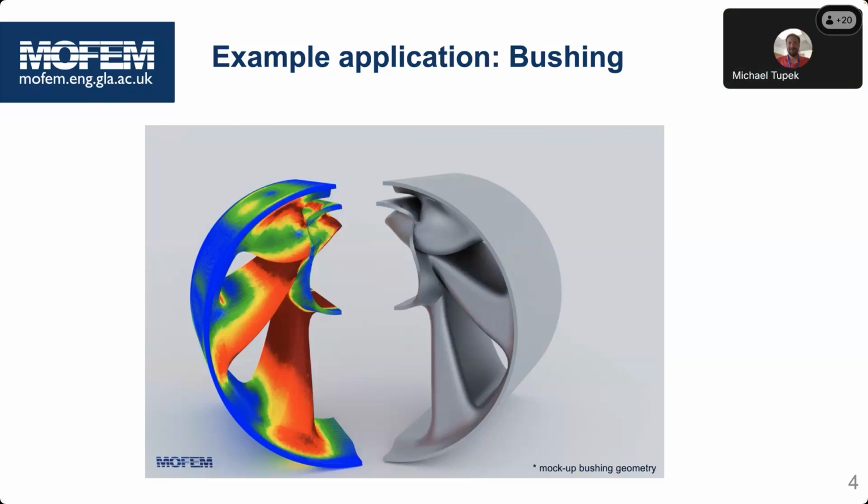So it looks like early on you guys were doing some pretty impressive stuff where you were explicitly representing the crack surfaces and evolving the front. And I'm somewhat aware that that's not trivial to do robustly. But more recently, it looks like you guys have been moving more to the cohesive insertion type of thing. I understand it's more elegant in the sense that you don't have to insert and change topology, but it has the limitation, of course, that the surface representation possibilities are limited, right? You're stuck on the surfaces that exist in the mesh, and that can add some bias and lack of convergence. So what is your sense of the trade-offs and your view of the future for these kind of trade-offs?